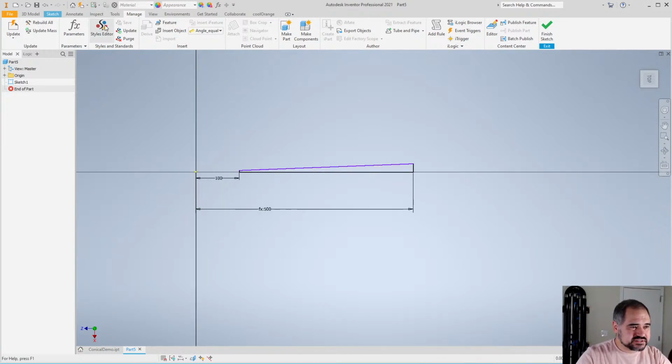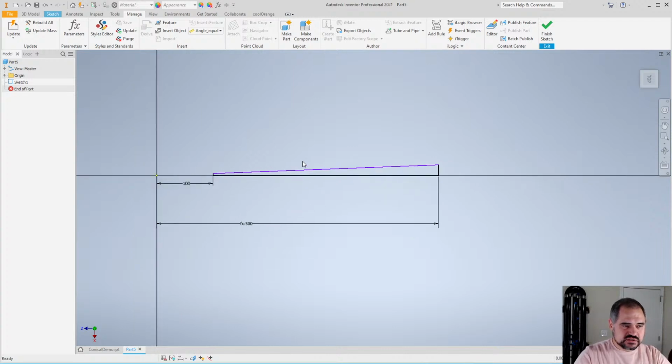Personally, what I like to do is define the taper of the instrument. If you imagine a line, a taper is like a slope. It's not an angle, it's just saying that for every 1 millimeter in length, you are getting, let's say, 0.05 millimeters larger in diameter.